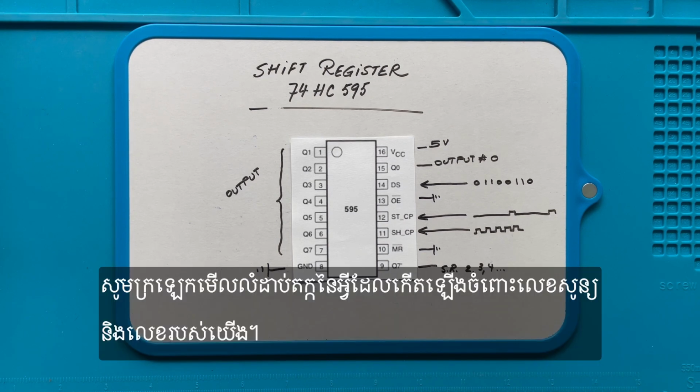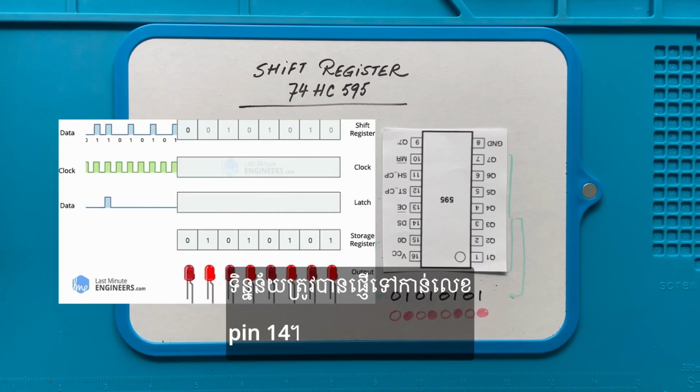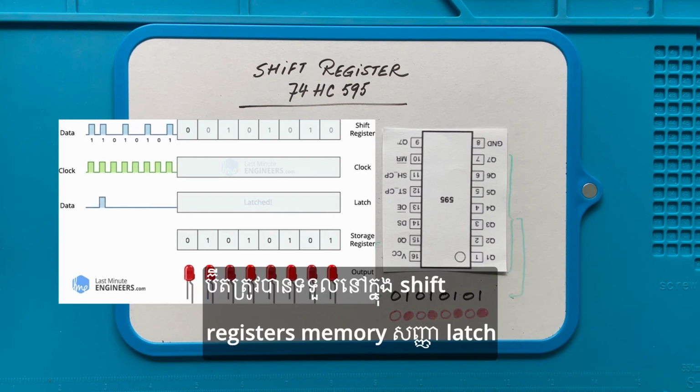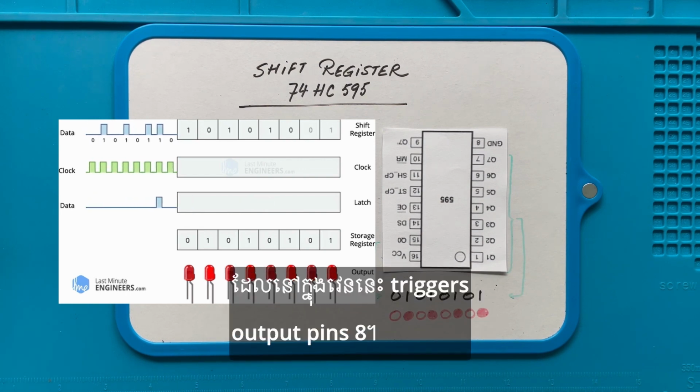Let's take a closer look at the logical sequence of what happens to our zeros and ones. The data is sent to pin number 14. The clock signal ensures that the data is sent in an orderly way. Compare this to the beat or the rhythm of a song. Each time a series of 8 bits has been received in the shift register's memory, the latch signal triggers the data to be released to the storage register, which in turn triggers the 8 output pins.